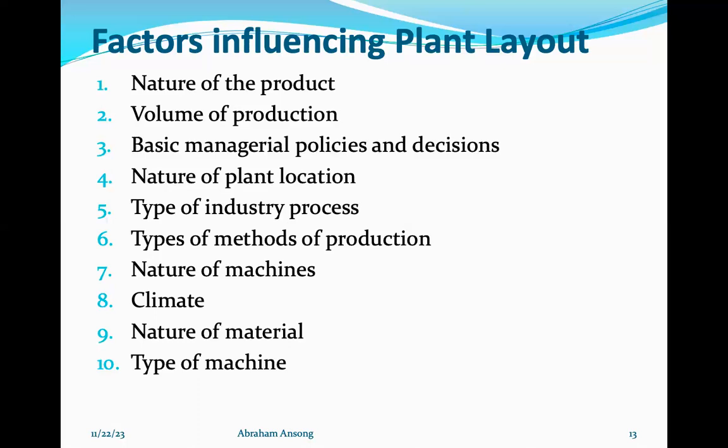All right. Batch production carries the production of goods in batches or groups at intervals. In this type of manufacturing, the product is standardized and production is made generally in anticipation of sales. In such cases, functional or process layout may be adopted. In case of mass production or standardized goods, line layout is the most suitable form of plant layout.